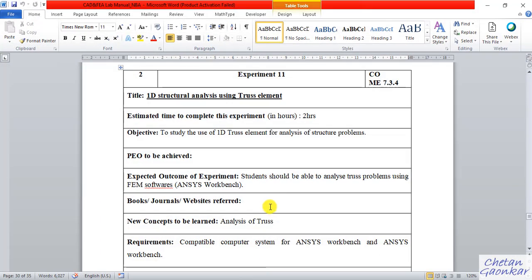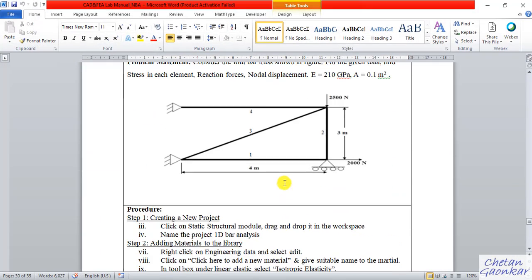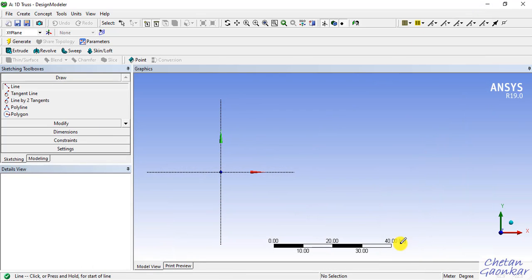the truss. Right now, if you look here carefully, this truss is in terms of meters. This is 4 meters, 3 meters, since this is 4 meters, this is 3 meters, also this will be 4 meter and this will be 3, 4, then this should be around 5 meters, which it will take automatically. But what I'm trying to tell you earlier is, since the dimensions are already in meter, we need not convert this into mm. So we'll keep it as it is.